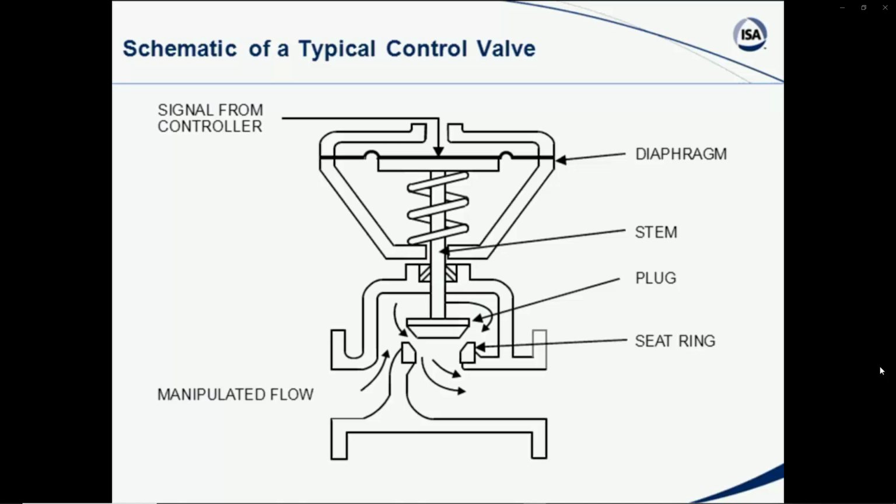These can be found in many different types of publications. One excellent course publication is the Fisher Control Valve Handbook. I think it's in its, I don't know what edition it's in now. This particular handbook goes back a long way, but in that handbook you'll find much good, useful information dealing with control valves, notably some material compatibility charts that help you select based on the corrosion characteristics or the erosion characteristics of materials of construction, both for the body and for the trim, the plug and seat ring, or whatever type of trim you have.